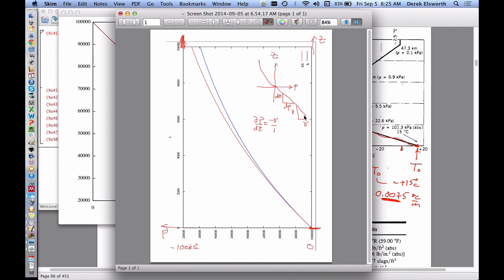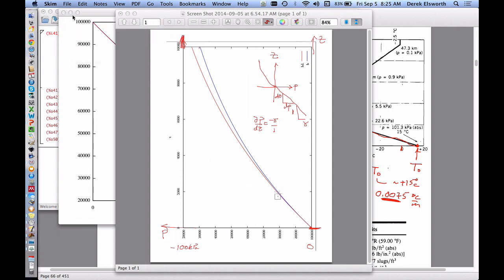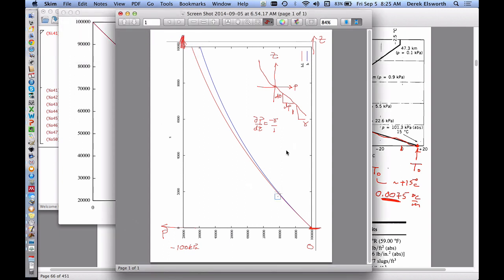And those triangles should be the same shape. They have the same units, and therefore they're the same shape. So we could calculate what the gradient of this curve should be at this particular point, and what would it be? I guess it would be equal to the unit weight. So if we would draw where this goes into the water, the gradient of this curve would be, the height would be 1 meter. This length here would be 10 kPa.